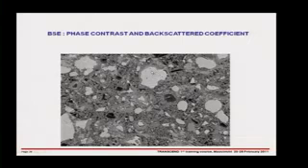So this kind of image we've seen many times before. This is your unhydrated cement. The unhydrated cement, on average, has the highest atomic number. We can see our calcium hydroxide. Here's our calcium hydroxide here. We can see our CSH, etc. And this is all due to the differences in atomic number.